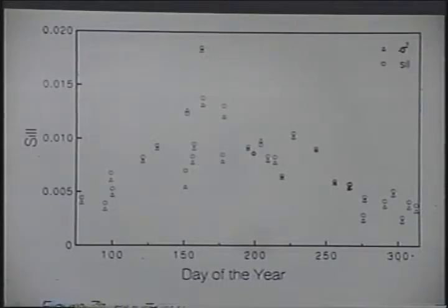Also shown on the slide is the variance for the entire NDVI domain. And what this shows, something that the equation also showed, but that I didn't point out at the time, is that for large values of h, theoretically, in principle at least, the variogram should approach the variance, or twice the variance rather, depending on how you express it, of the entire population. And this shows that indeed over the area we did obtain that.